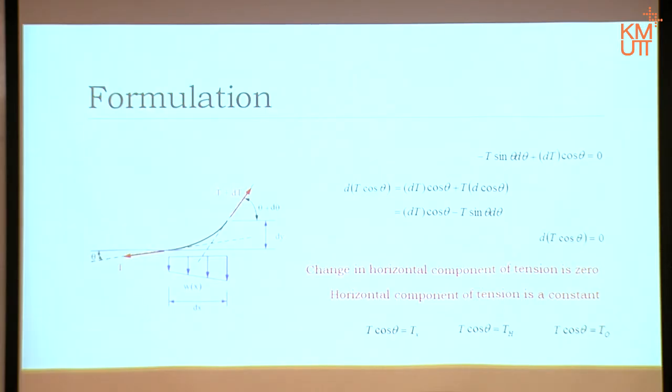Okay? Apparently, it also equals, I will explain later, the tangent at the origin. The reason is because the origin is the lowest point, remember? Meaning the tangent line is horizontal, meaning tension is on the horizontal line. Since it's constant, therefore it is the tension there as well.